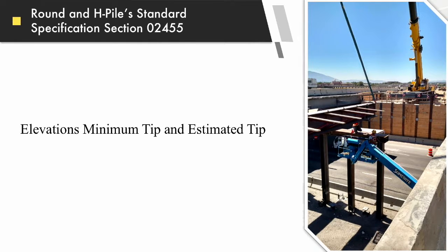The way the H pile is set in an abutment or a footing is critical, and the contractors know that, but I've been on projects where the pile buck turned the H the wrong way, and at that point, the capacity that the designers have designed for that structure is totally blown out. So as you're looking at your plans, make sure you're looking at the orientation of the H in your H pile. And thank you, Julie.